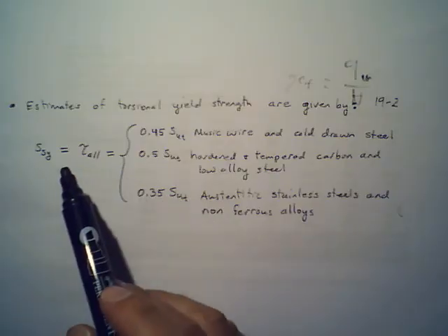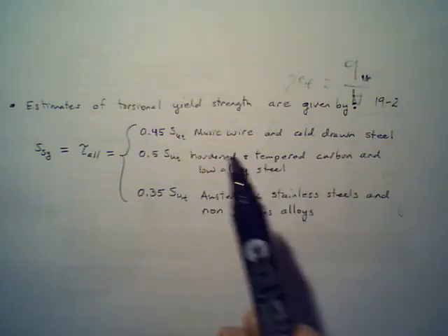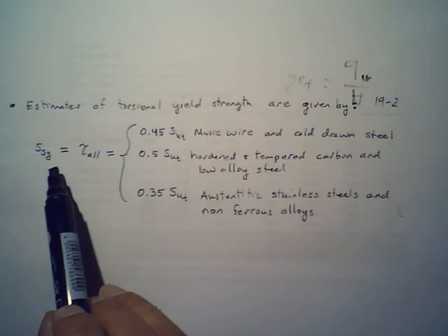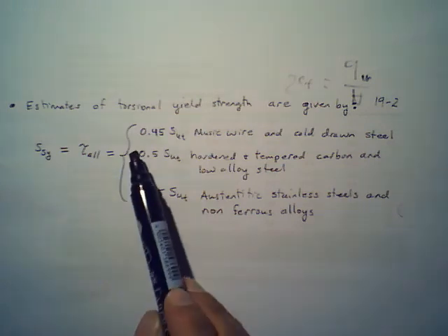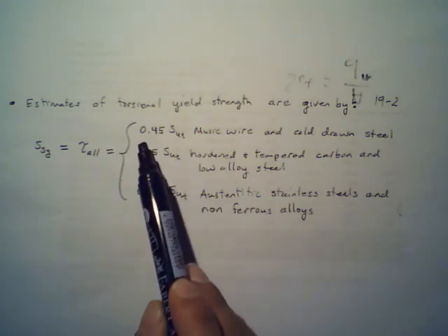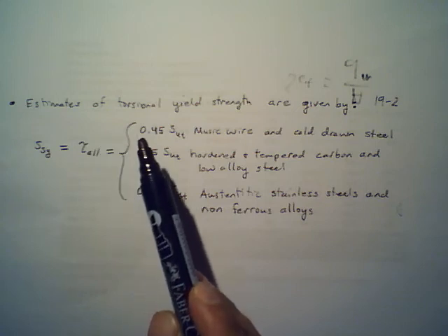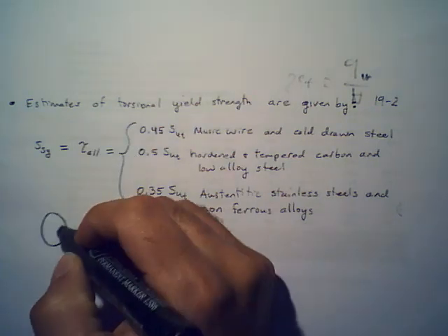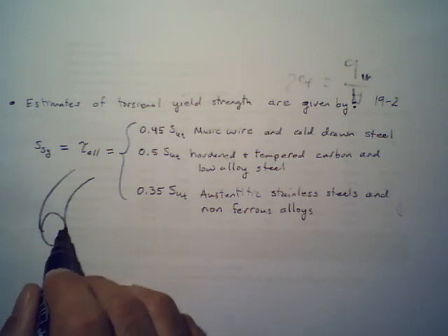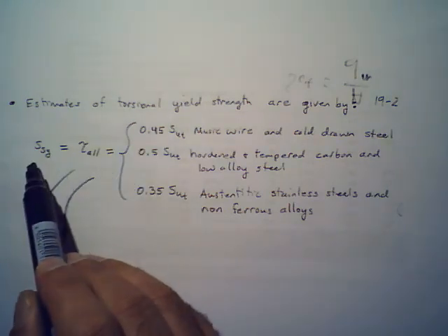There is one last thing regarding compression springs: when we find the SUT, you can also find the maximum allowable shear stress. We are going to look into where you can use those and how we do the safety factors later on. We know the spring will fail because of shearing. So let's say this is a spring wire. This is a portion that is going to be subject to torsion or maximum shear stress based on the equation that I provided earlier.